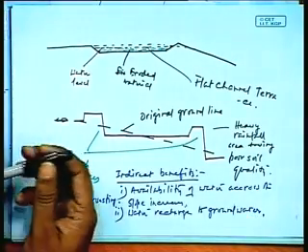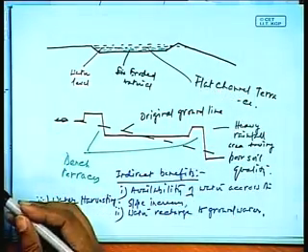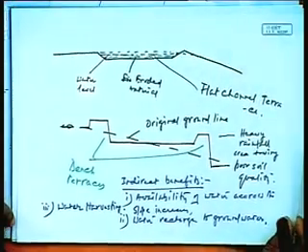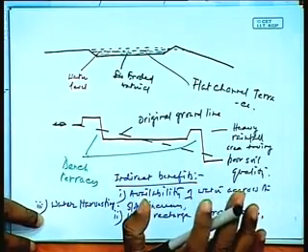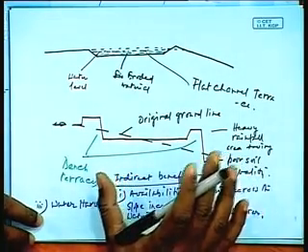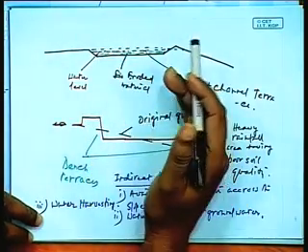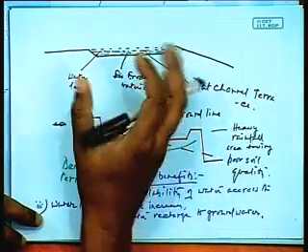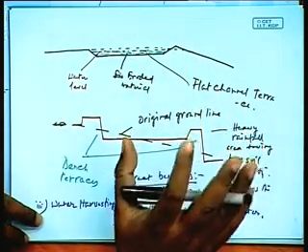Here we see the terraces, the flat channel terraces that we make, and bench terraces. These are the different types of terraces and their uses. There are some design aspects, and they are very simple. Depending on the structure of the slope, the availability of the slope, and the rainfall pattern, you think of what kind of terraces you are going to have.